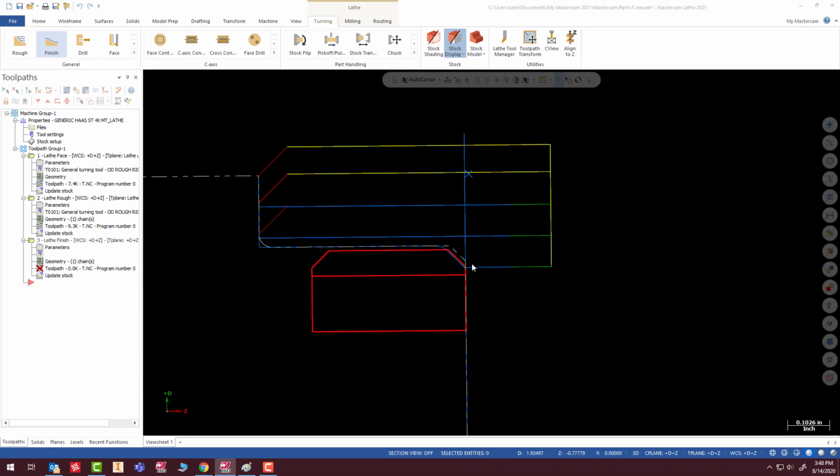So when it takes a pass and plunges down in here, it's taking a much heavier cut. And even though these lathe tools are fairly rigid and heavy duty, it still will have a little bit of deflection, and what we'll end up with is an inconsistent finish. You'll have a nice finish here because it's only taking 10 thousandths, and then you're going heavy, and it's going to be a different finish. It might still be okay, a decent finish, but it's just not going to be consistent. So I try to get everything so it's a consistent finish.